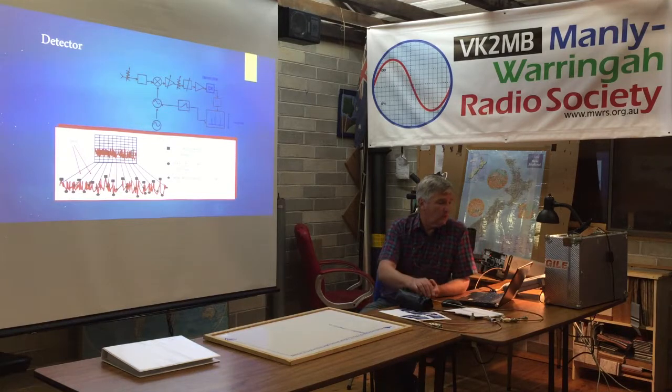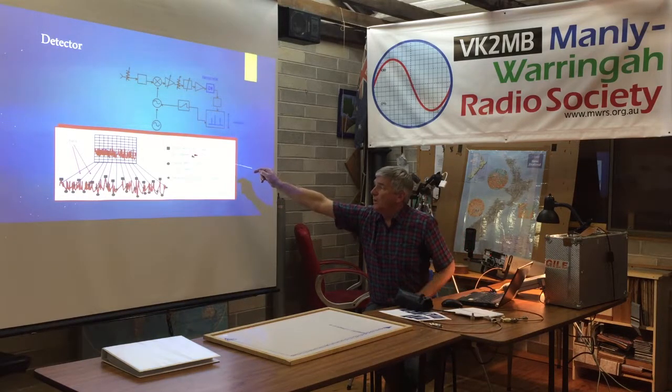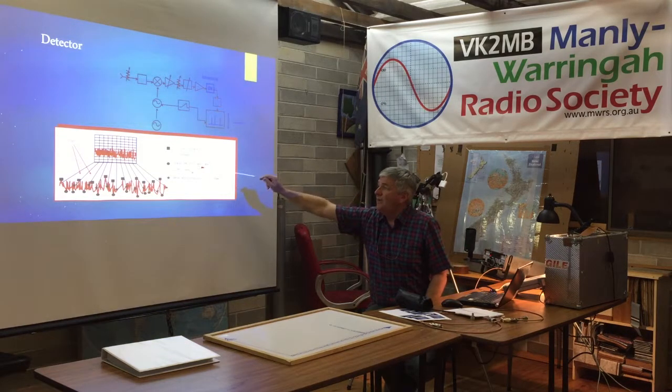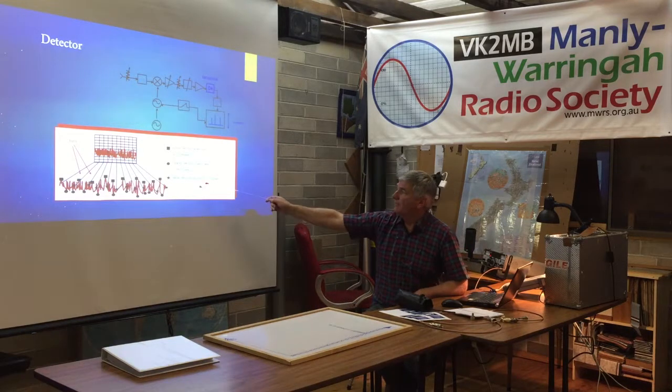Okay, so the next thing, just following the chain through, is the detector. So again, with modern spectrum analysers, you can select different detectors, not just one detector. So there's a couple of them there. There's a positive detector, so it'll in fact detect the largest value, or you can have a negative detector to detect the smallest value, or you can have a sample.